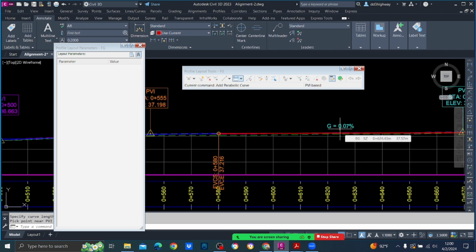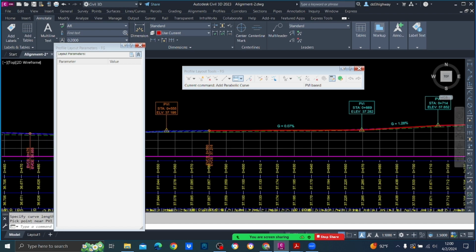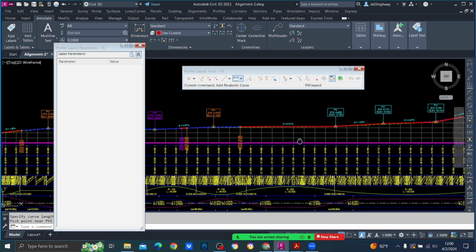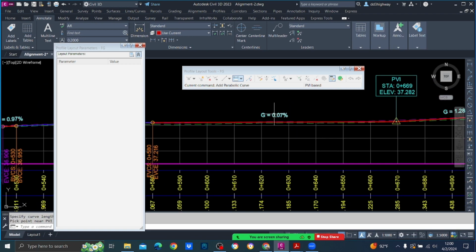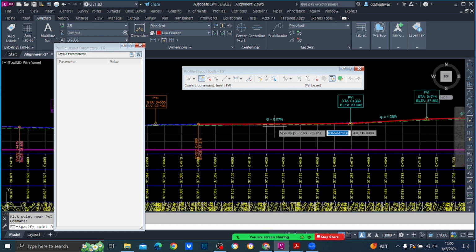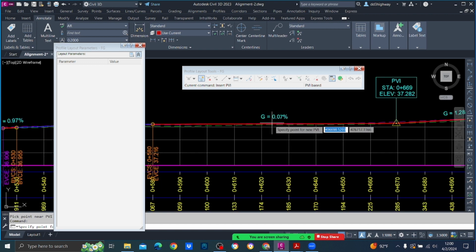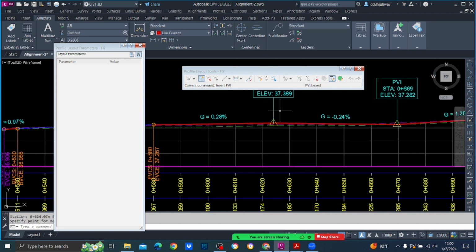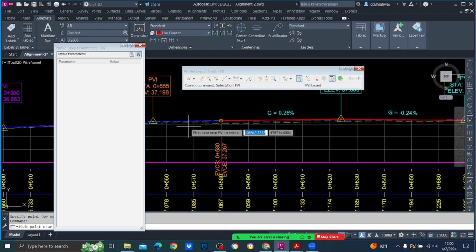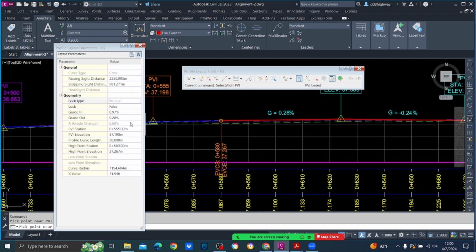Now the problem here is going to be 0.07. Okay, so you can't do that. So for that you will have to insert some IP here, somewhere here, not curve, some IP. You select this IP, and you see grayed out is 0.28, you make it 0.3 minimum.